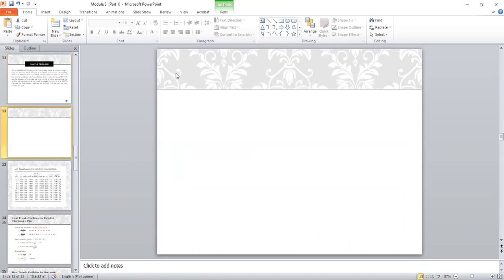So let me just write here the formula that we need to substitute everything. So we'll have Nu, so hD over K, and you have 0.027. I will substitute the Reynolds number already. The one that we got is 1.123 times 10 raised to 4.